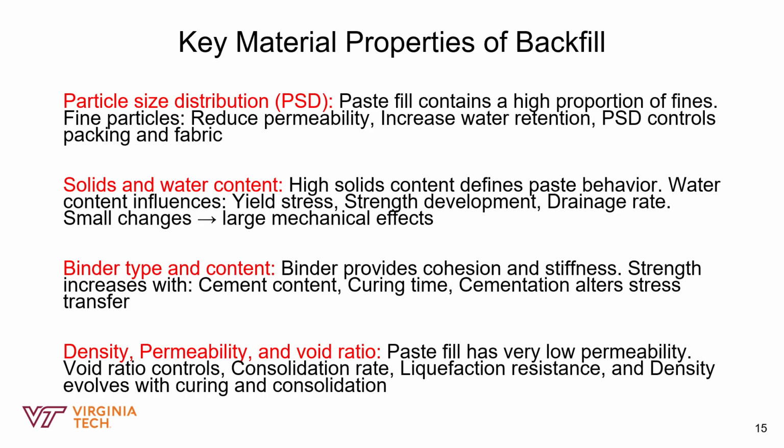And the last one, we have the density, permeability, and void ratio, and they control the risk. The void ratio is simply the measure of the empty spaces in the mix. If the void ratio is too high, the material is prone to liquefaction. We want a dense material, a tightly packed material, and so we want the void ratio to be low.